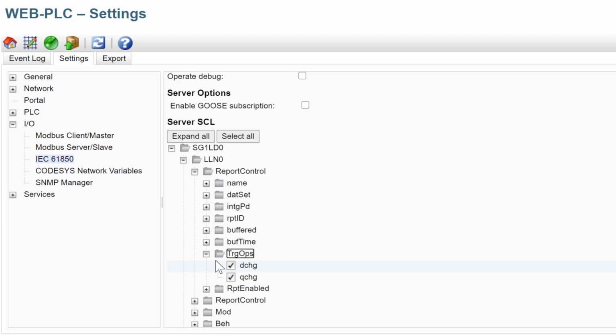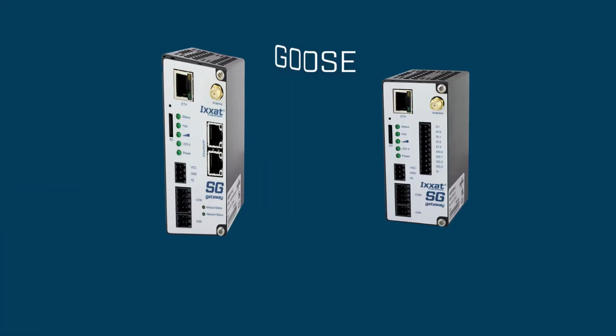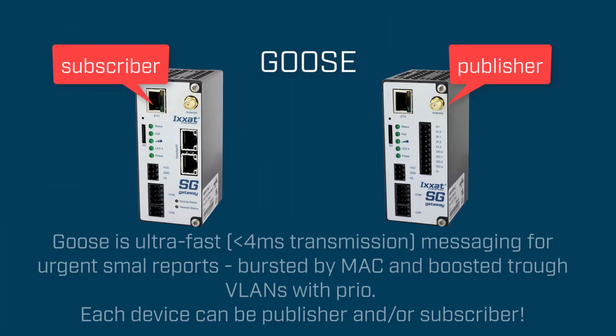Note that if the Select All button is clicked, all data points and all trigger options are activated, even if some data points or triggers are set to false in the CID file. So, if you clicked the Select All button, recover the report control block trigger settings by deselecting the unwanted trigger options. If reporting is still too slow, Goose can be used, which is really fast.